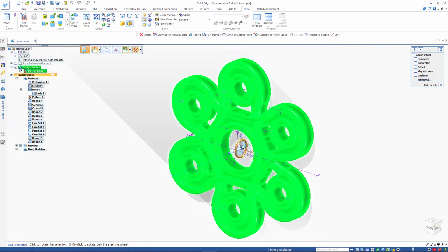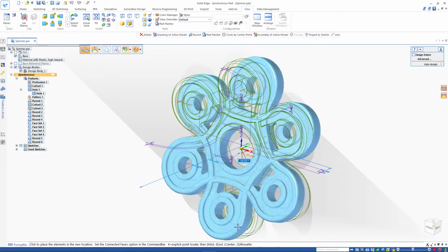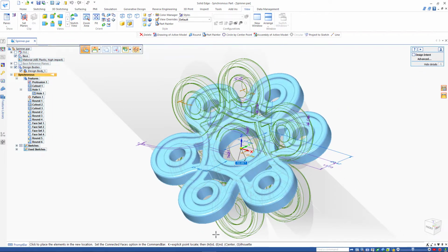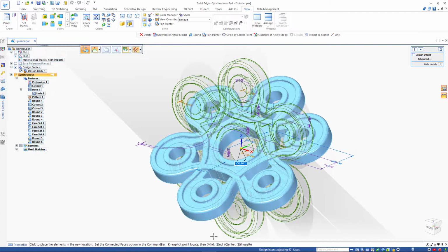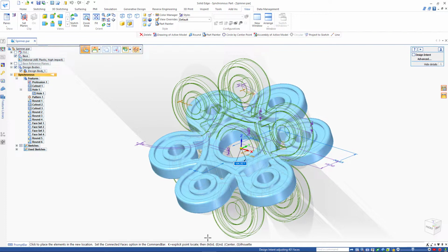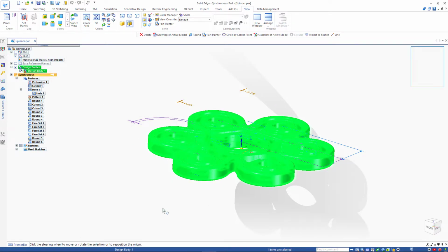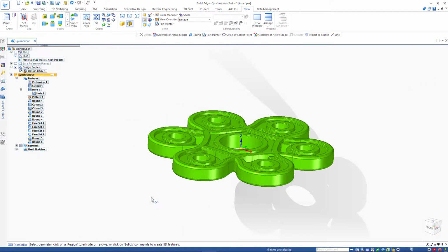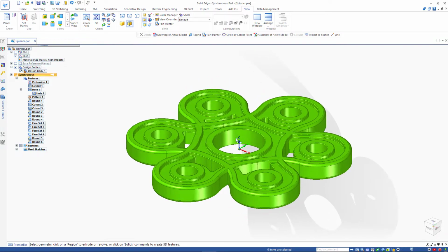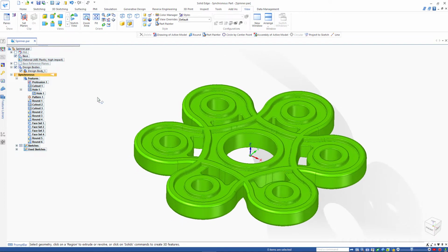I click on the torus of the steering wheel, and I want to rotate it in this direction. So I see in my preview there the value, the angle value, that's a negative number. So I'm going to type in minus 90. Maybe a positive for you depending on the orientation of your steering wheel. And then I'll just right click to accept it and click escape. All right, so now that's in the correct orientation. Z is pointing up toward the top, which is the way that I want. That's the way my draft is going to be measured.